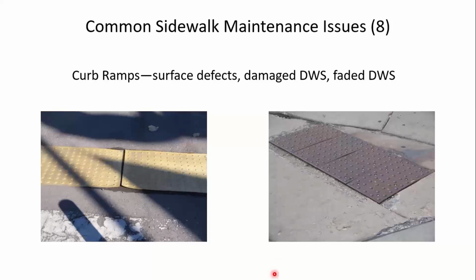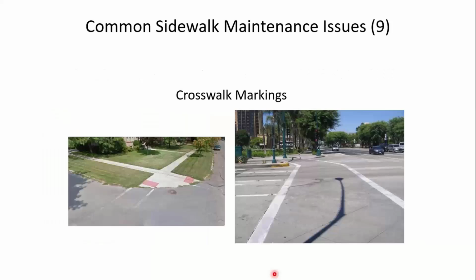So the ADA features, in addition to the rest of the walkway, need to be checked for these sorts of issues or concerns. And then crosswalk markings. Here on the left, it looks like at one time this agency did mark this crosswalk, but I would say, to me, it needs to be renewed again, restriped with new paint.